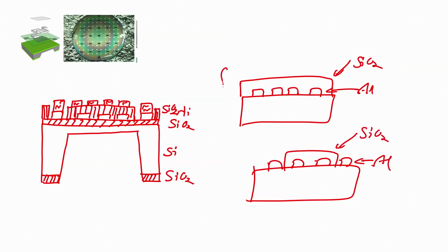If I have this wafer with SiO2 covered on aluminum interdigitated electrodes and I want SiO2 to only cover these two parts of the design, I have to perform lithography, and finally dip this wafer in BHF, correct. Why BHF? Because BHF is the etchant for silicon dioxide.